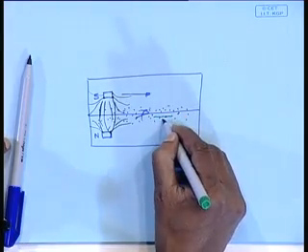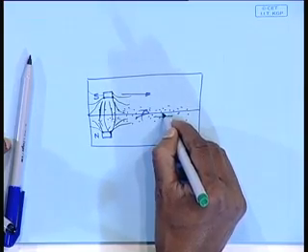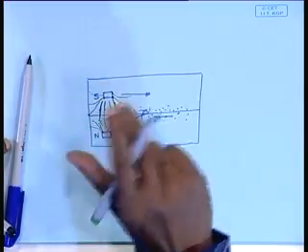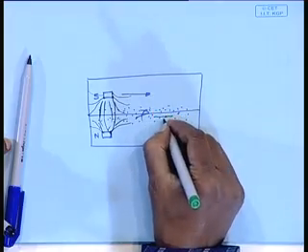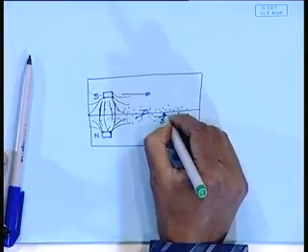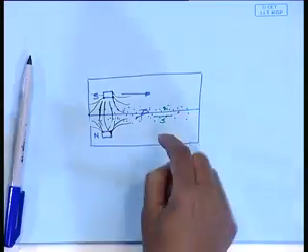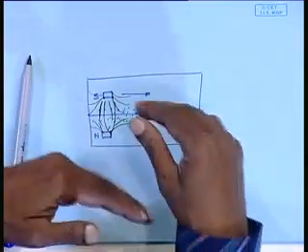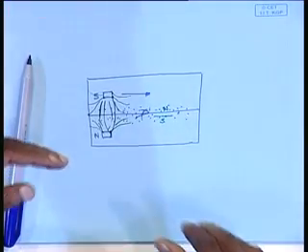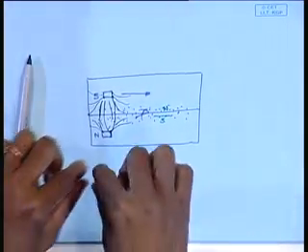In this discontinuity, the side closer to this will become a south pole and the other side will become a north pole, isn't it? Just reverse magnetic fields will form. And again there the magnetic lines of force will be disrupted. So, those iron powders will align themselves along that crack, right, and the crack will be visible.